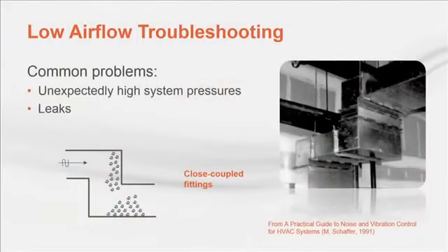And speaking of installation, don't forget to visit the construction site and monitor duct installation practices. Even innocent modifications can unexpectedly change system resistance, result in a system effect, or both. Leaks are another common problem, primarily in the unit connections or in the duct systems, but potentially at the fan bulkhead wall as well.